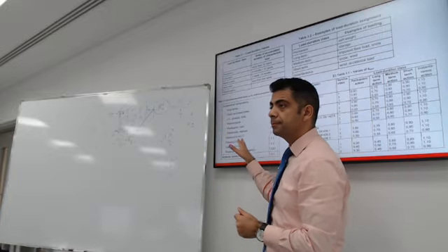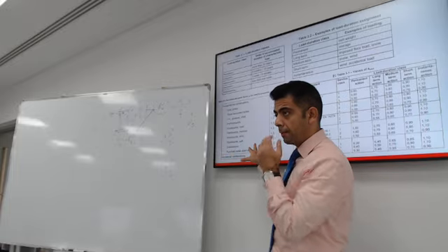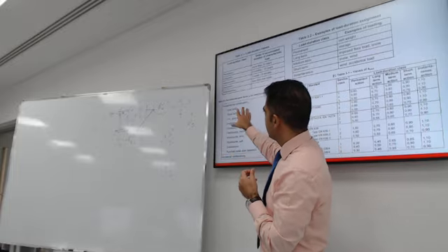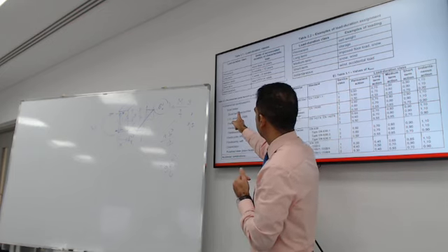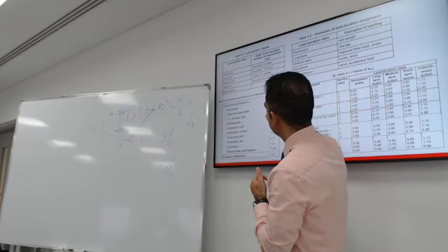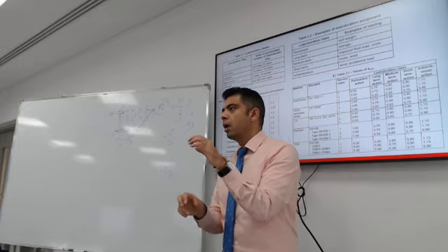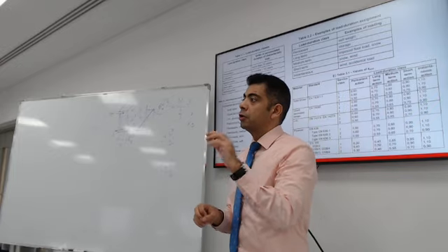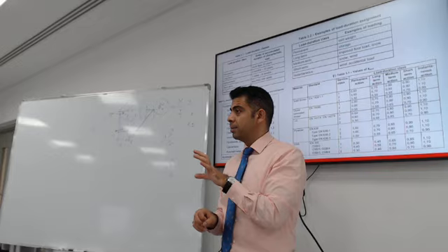So this is for the SLS surface load? This is for ultimate limit state. These are the factors for gamma M. So if you're using solid timber, the factor is 1.3. So when you're dividing by 1.3, are you increasing the strength or decreasing the strength? Decreasing it quite a bit.